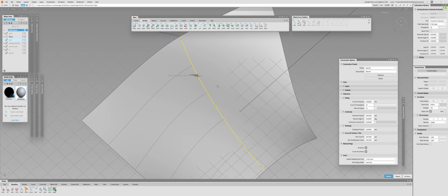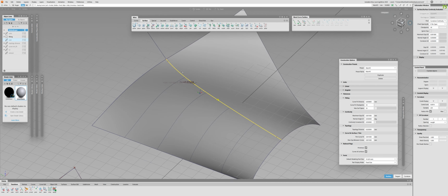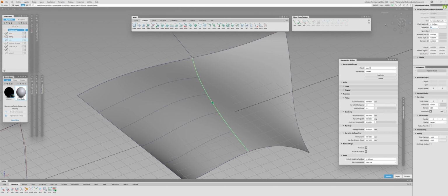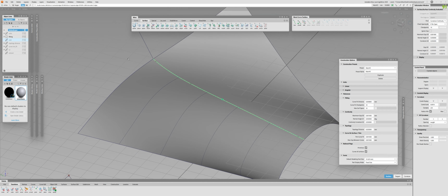All right. So you see, the more checkpoints you have, the more accurate reading you will get. The original one was 10, and for 10 it's perfectly continuous. For 20 checkpoints or 30 checkpoints, it's not. And by the way, a small hint. Let me deselect and use the surface continuity again. If I use surface continuity, click the middle mouse and drag to the right, it will increase the amount of checkpoints right here. Look at the top right. So click middle mouse to the left or right, and it will increase or decrease the value on the fly.